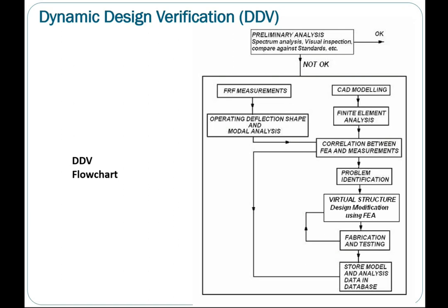So if you can shift your natural frequency away, then you can have the resonance issue rectified. So how to shift it? By modifying the machine that is under resonance or has these dynamic design issues.